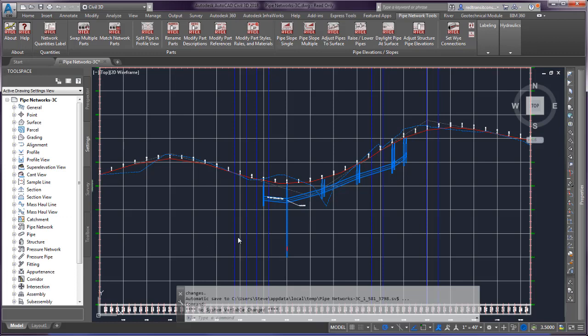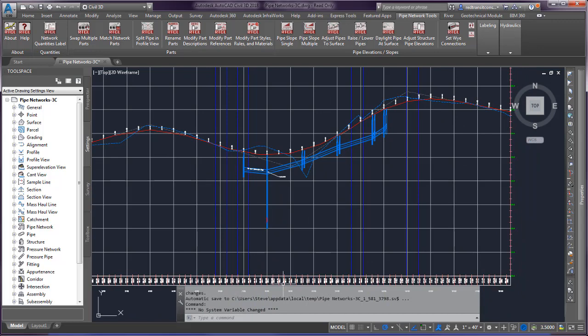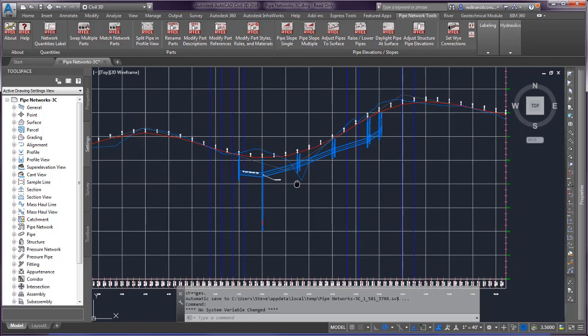The idea behind this command is to give users the ability to label their pipe elevations at intervals in their profile view. And to do that within Civil 3D, one would have to draw a profile along their pipe invert, centerline, or crown, whichever it is that they desire to label the elevations of the pipe, create that profile, and either assign the band set at the bottom to reference that profile, or apply some unique label style to the profile that will generate those labels.